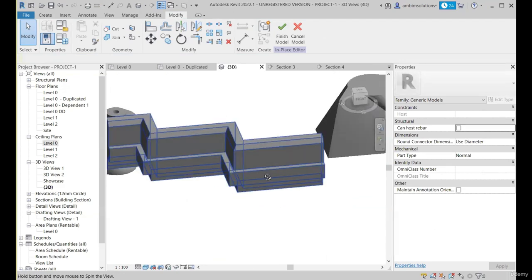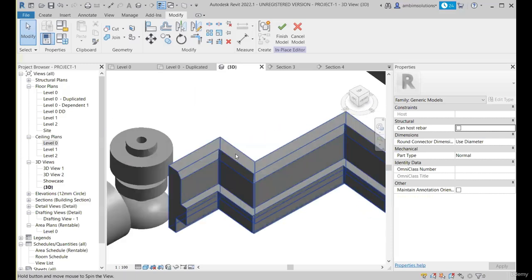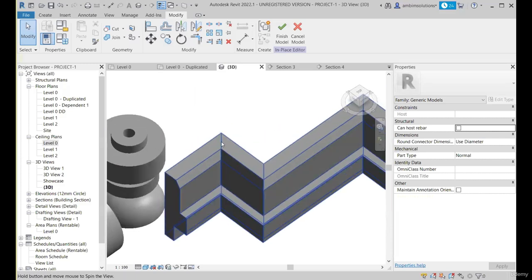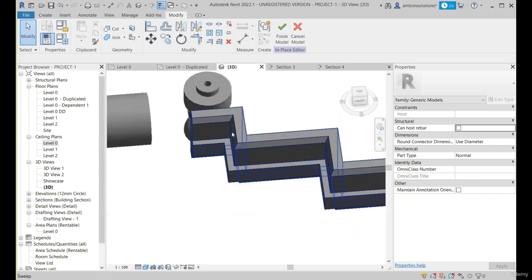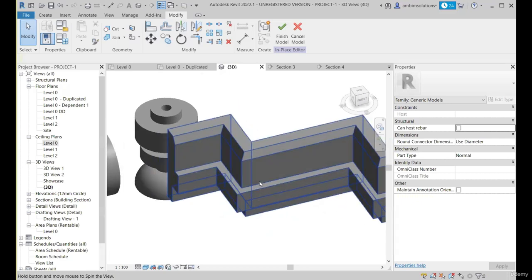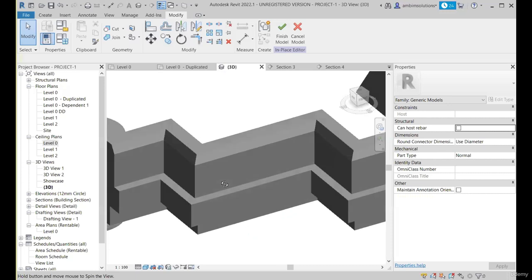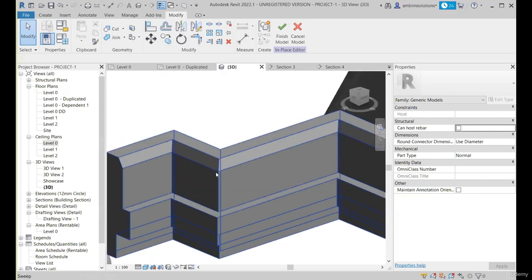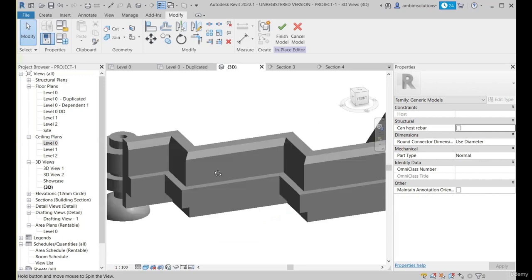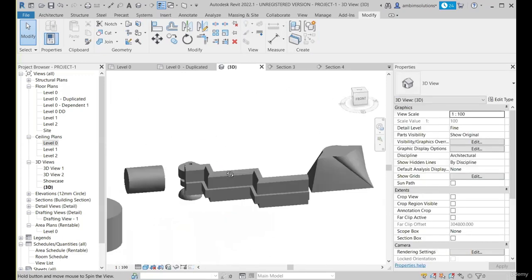Okay, in this way. The error that we have found earlier when we sketched the profile was because the profile that we have created was exceeding this part. So whenever the profile was traveling through this section, it was unable to form the proper junction here. So because of that, the error was populated. Now that we have adjusted the profile, we are able to have proper junctions formed. So we are not facing any kind of error. Like finish, you can see the sweep has applied.